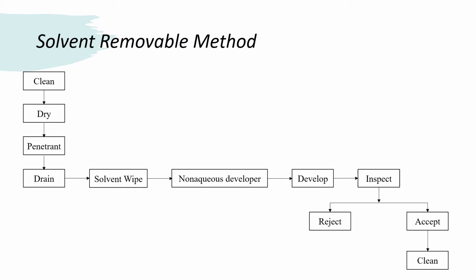The solvent technique is most often applied for the inspection of either a few small parts or for localized inspection, such as in situ inspection of pipe welds and pressure vessel welds, and is most amenable to portability.